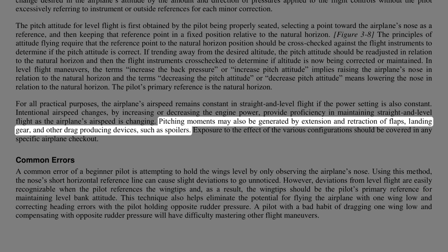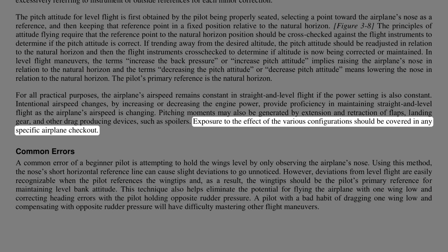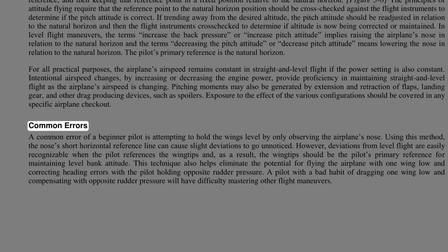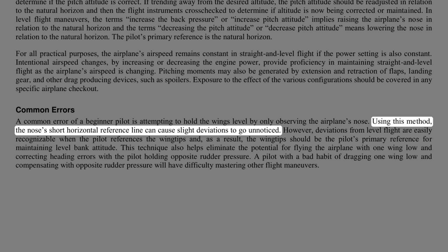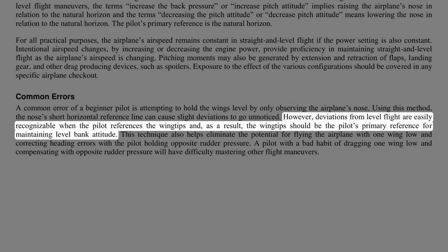Pitching moments may also be generated by extension and retraction of flaps, landing gear, and other drag-producing devices, such as spoilers. Exposure to the effect of the various configurations should be covered in any specific airplane checkout. Common errors. A common error of a beginner pilot is attempting to hold the wings level by only observing the airplane's nose. Using this method, the nose's short horizontal reference line can cause slight deviations to go unnoticed. However, deviations from level flight are easily recognizable when the pilot references the wingtips and, as a result, the wingtips should be the pilot's primary reference for maintaining level bank attitude.